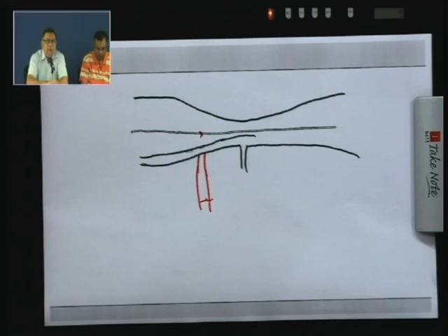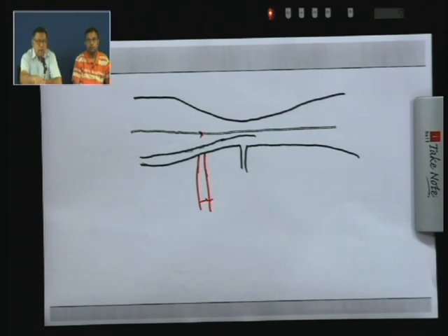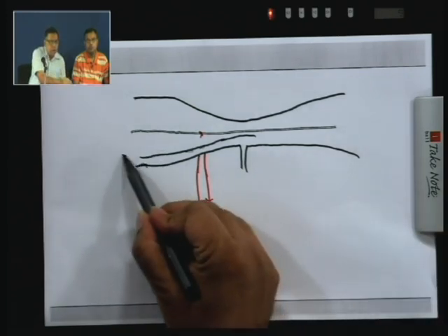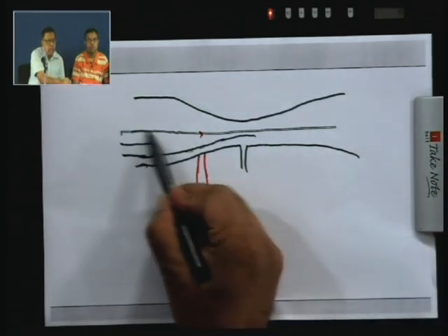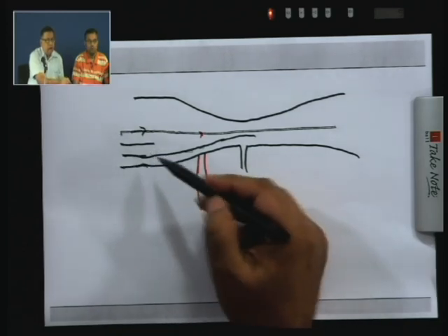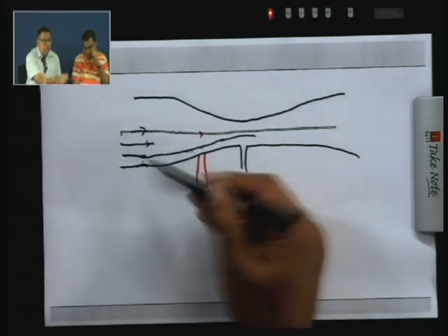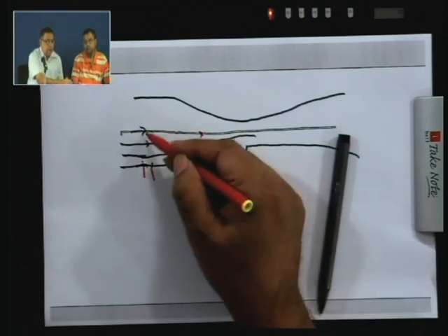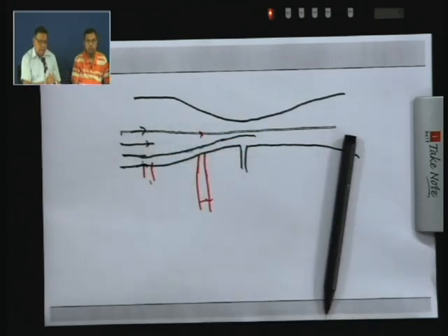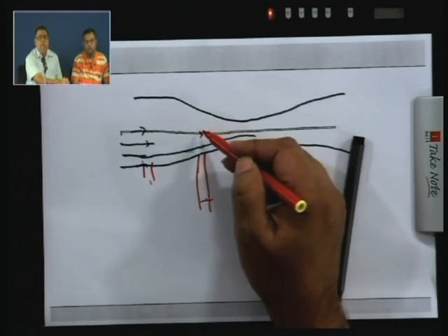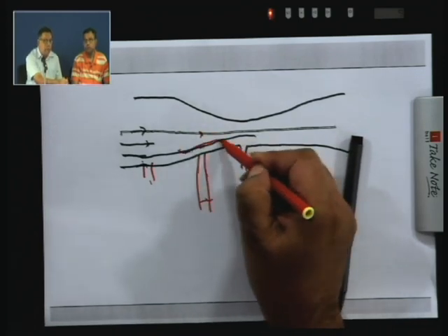Now, we have been applying the hydrostatic formula that the pressure increases linearly with depth in the vertical direction. Now, that is true when the fluid is flowing also, provided that the streamlines here are horizontal. So, if you look at the streamline pattern, upstream here the streamlines, for inviscid flow, will be parallel. So, you would like to put the tap somewhere here, so that in this vertical direction you can apply the hydrostatic formula. Here if you want to apply it, there will be a significant error because of the curvature of the streamlines.